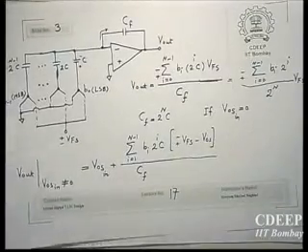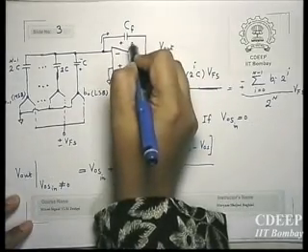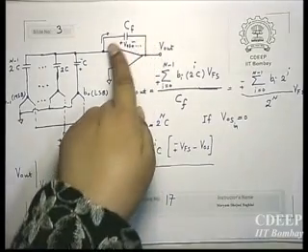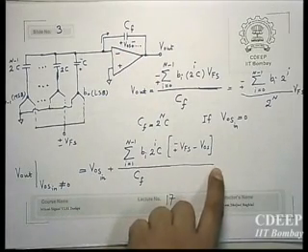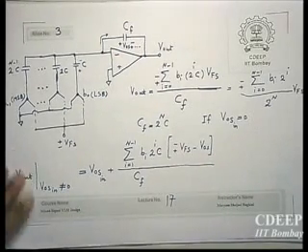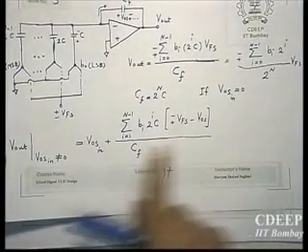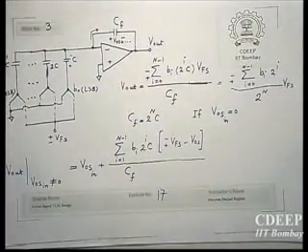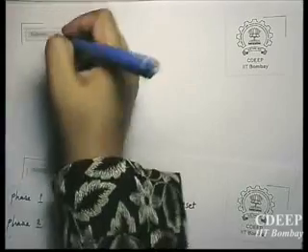Okay, so now when it is connected, you have something like this: V offset plus other things. And V out is minus this voltage, right? Therefore, whatever you had in the form of V offset, now you will have a minus V offset in V in. V offset in will get compensated. So what remains is only this factor, which is eventually V offset appearing as an error in the gain. Okay. So, do you want me to prove it is a gain error or will you do it?